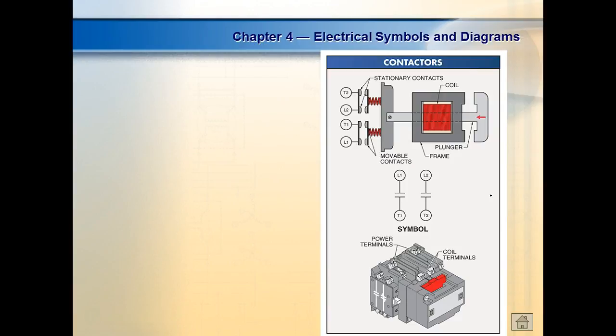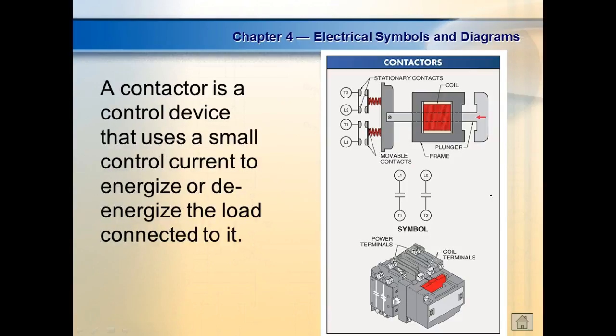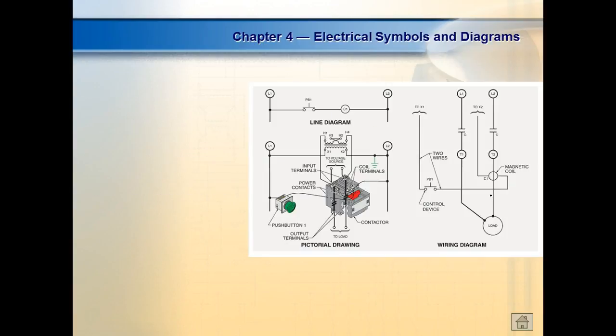So this would be a contactor, not a control relay. Control relays are going to be real small little things. All the contacts of a control relay stay in the control circuit. That's why they're called what? Control relays.